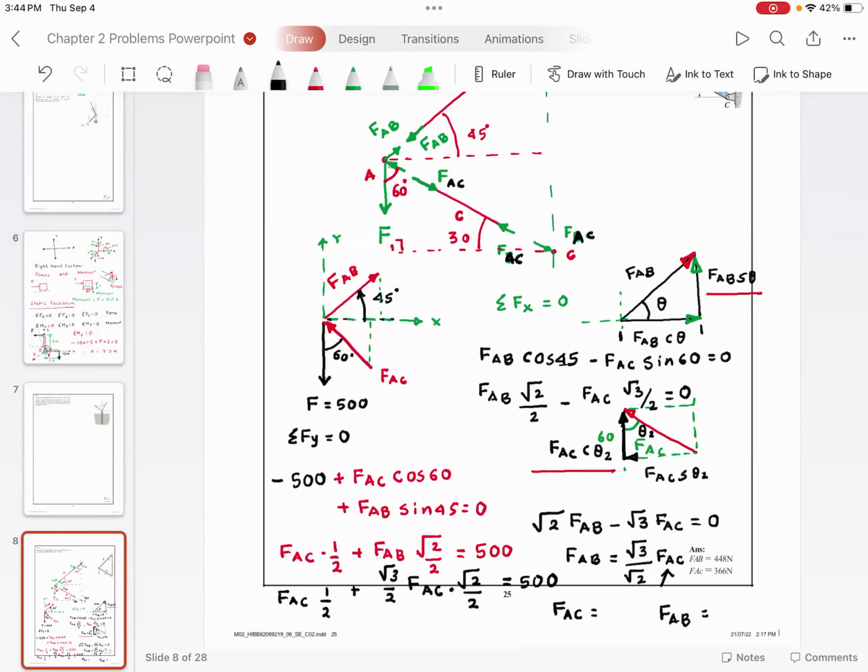Once again, let me explain. You have a truss. By the way, there is an entire chapter on truss that just deals with this, so make sure that you understand this. This is also called the method of joints. All the joints are in equilibrium. It means all the forces in x direction, y direction and z direction will cancel each other out.